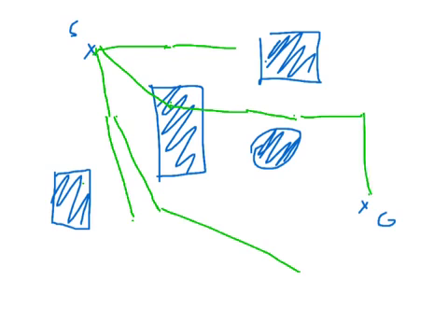Now what we would do is we would inspect the path only after it has been found. So we know this is actually a path, and now we spend time only to check whether it's in collision. So we can say, well, this path is in collision, or at least some segment of it is unusable.